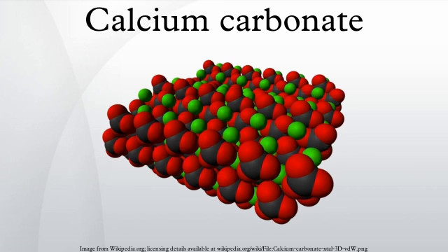Addition of HCO3- will increase CO32- concentration at any pH. Rearranging the equations given above, we can see that Ca2+ equals Ksp divided by CO32-, and CO32- equals Ka2 times HCO3- divided by H+. Therefore, when HCO3- concentration is known, the maximum concentration of Ca2+ ions before scaling through CaCO3 precipitation can be predicted from the formula.